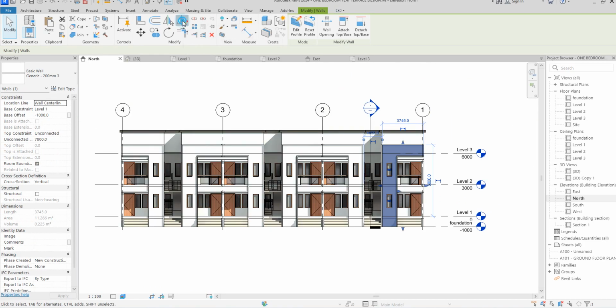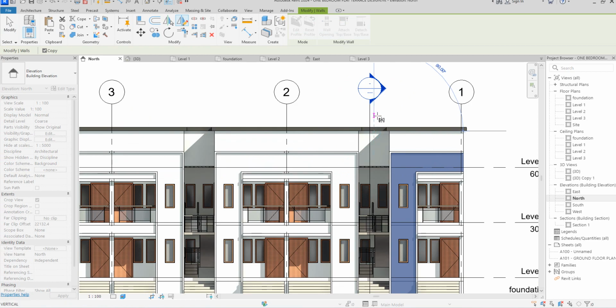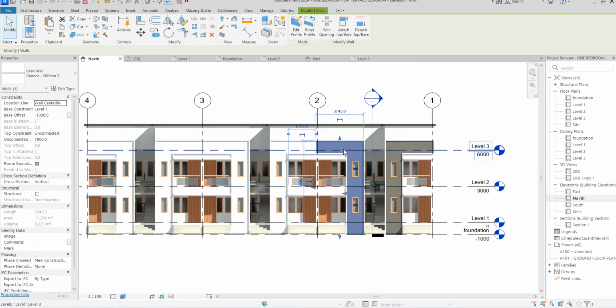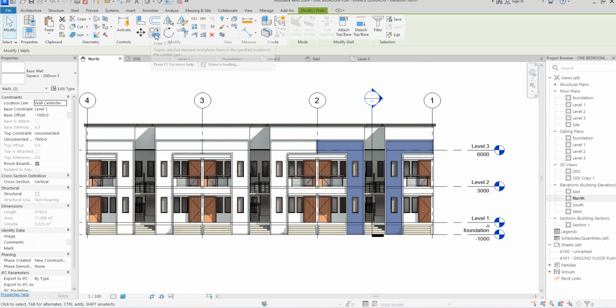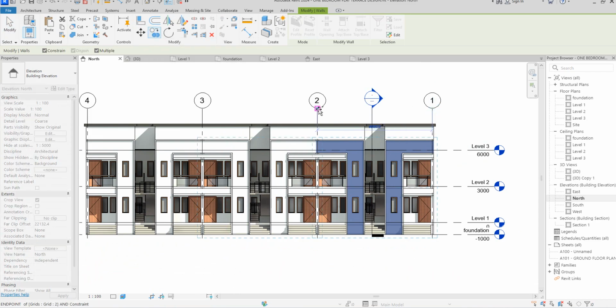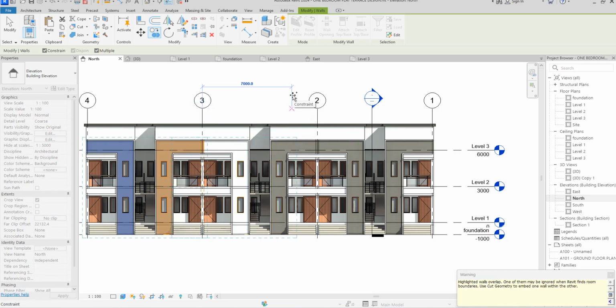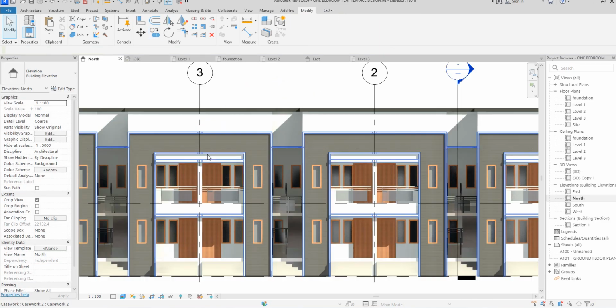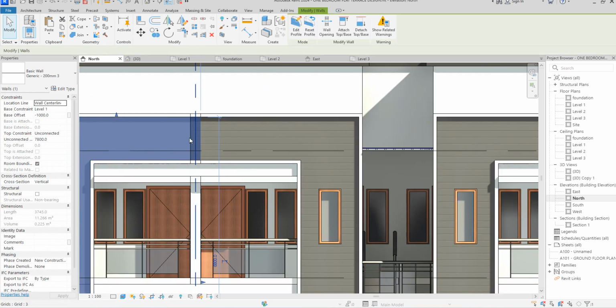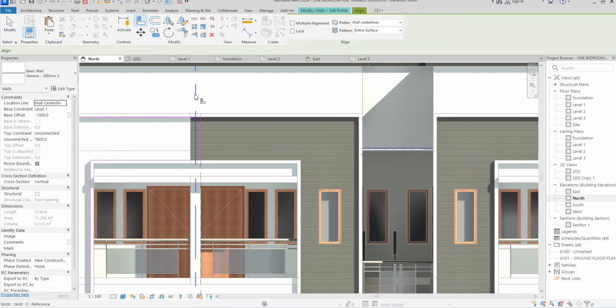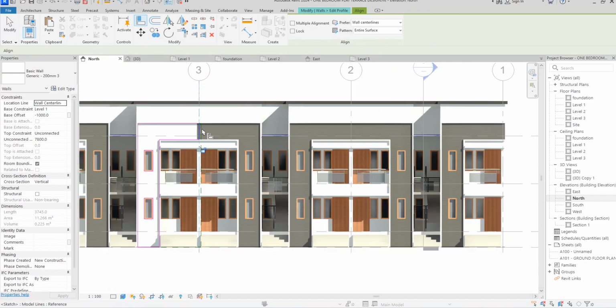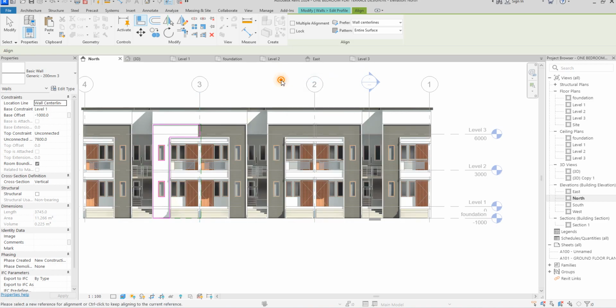Click on it, so you mirror it as well. Good. So you now need to select and start copying them from here. You copy. So what is it saying? It's saying that the walls collapse, isn't it? It doesn't matter, just continue to work. When you get there, you work on this one. Now you can later adjust all of these to fit into the position where you want them to be. So edit profile, you just click here, then adjust this one. So click finish like that.